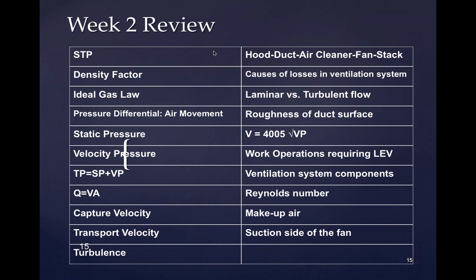Okay, back to work. Centrifugal separators, you see quite a bit of those because they're less aggressive in terms of blocking the flow of air. You get a lower static pressure drop across centrifugal separators very frequently. They only work very well for relatively heavy particles. The way that they work is they spin the air, and the larger particles get thrown to the outside, and they drop down to the bottom where they can be discharged.